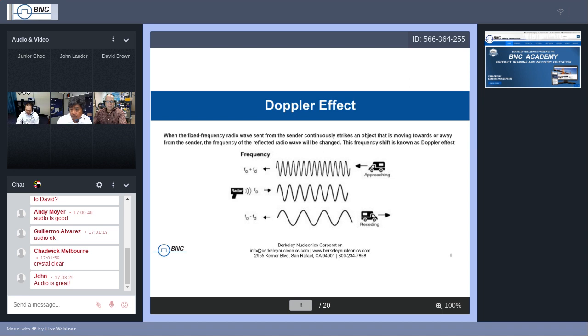In order to calculate the velocity or the speed, you would actually have to look at the frequency shift. So as you can tell, again, the return line, that frequency will be different from the transmission. That frequency shift is actually what the Doppler effect is, or some may call it the Doppler shift. By knowing exactly what this frequency shift is, you can calculate the velocity instantaneously. Due to the fact that this is a continuous wave, your results will always be continuous, and you can instantaneously measure that rate of change of the range of that target object.